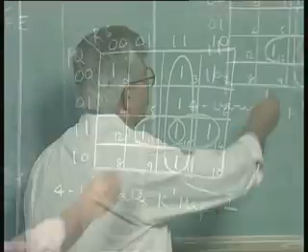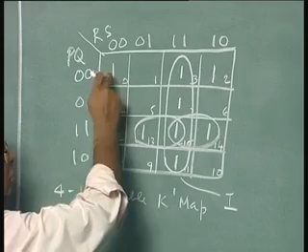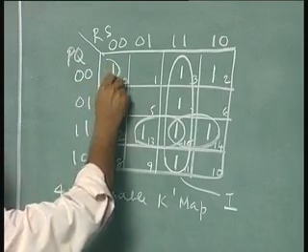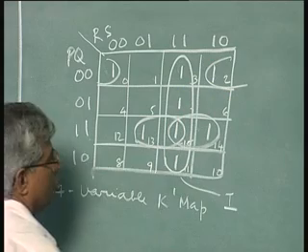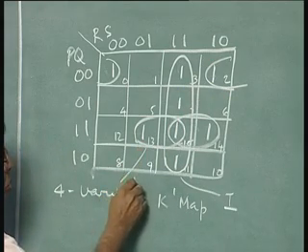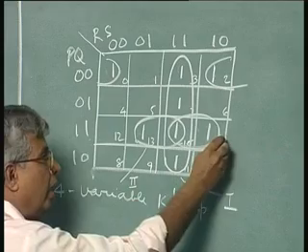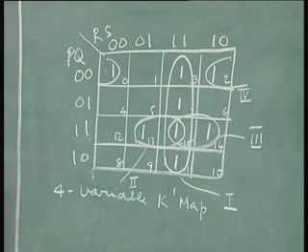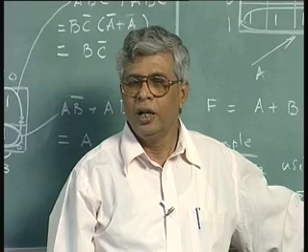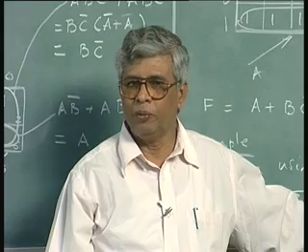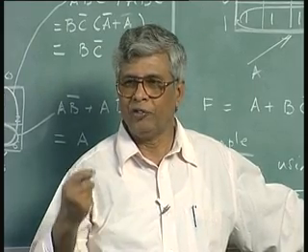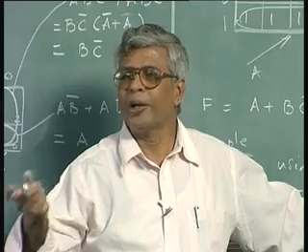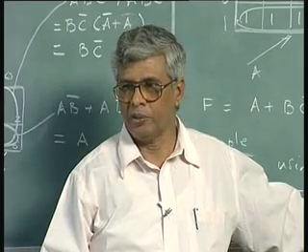So, that way I do not have to mix this here, because this is going to be combined, this is going to be combined, this has not been combined anyway. So, I will combine these two. I will call this 2, I will call this 3. There are now 4 groups of ones, and for each of them I have to write a logic expression, a sum of product expression. Then my final output F is the sum of all these product expressions, SOP, minimum sum of product.